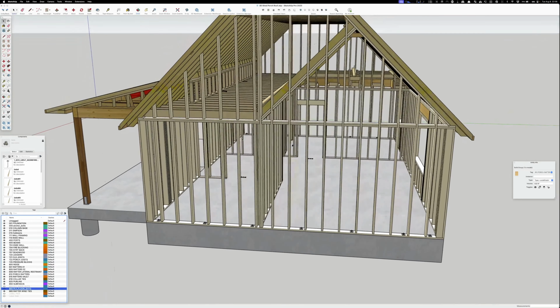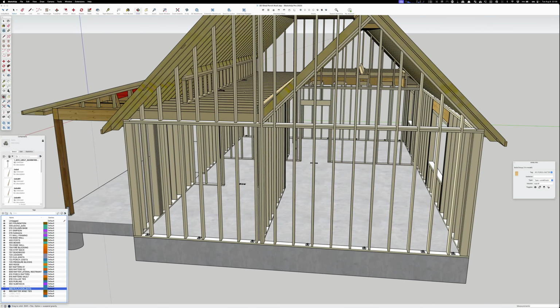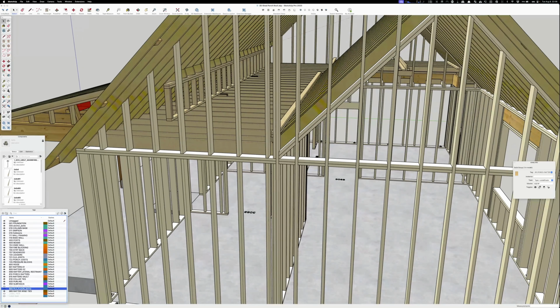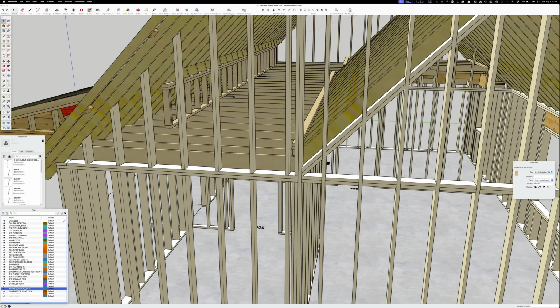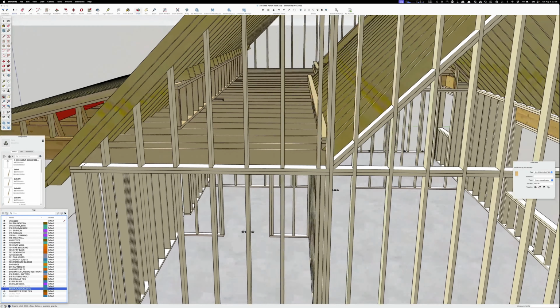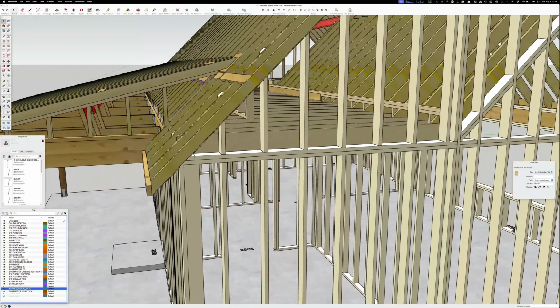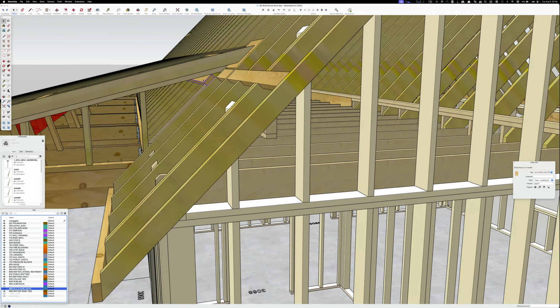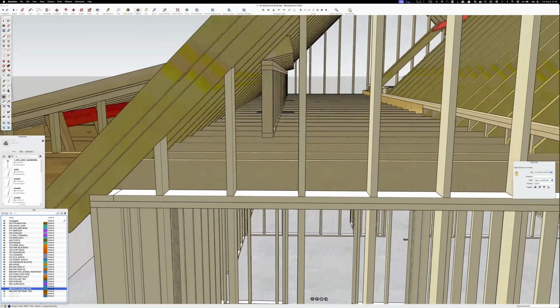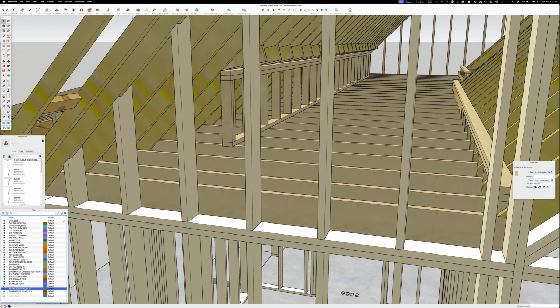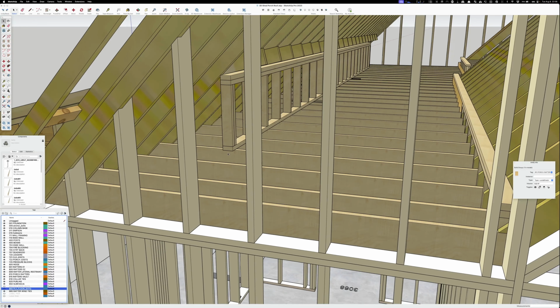So pretty much all the walls can be considered load-bearing. Then you build a wall, a little knee wall, and you snug it up underneath the rafters. So you're taking the load off of this 2x4, which would be sagging the main roof a little bit. And now you're transferring, since all these are nailed into the side of the rafters, you snug it up, you're transferring that load down across these joists.